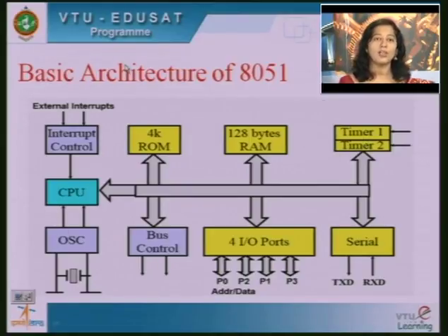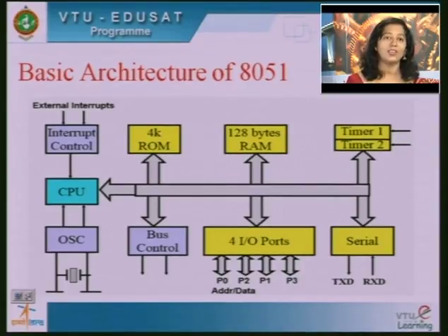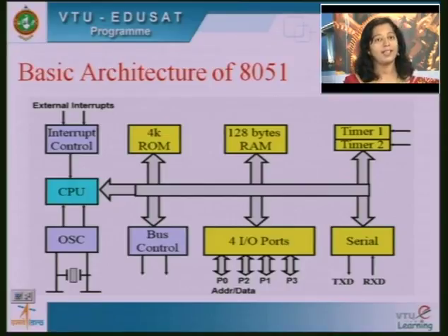So when some process is running, you can always interrupt. Suddenly some data comes in through the serial port, you can send an interrupt to the presently executing program and say there is urgent data to be taken in. Then the processor will stop its work, adhering to the interrupt. It will come and take in the data, store it in some location, and then once the interrupt is heeded, it will go back and continue its previous work. So all these things we have discussed.